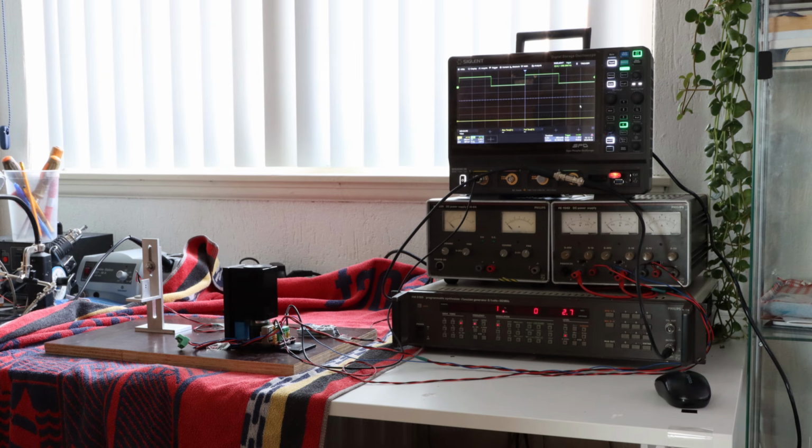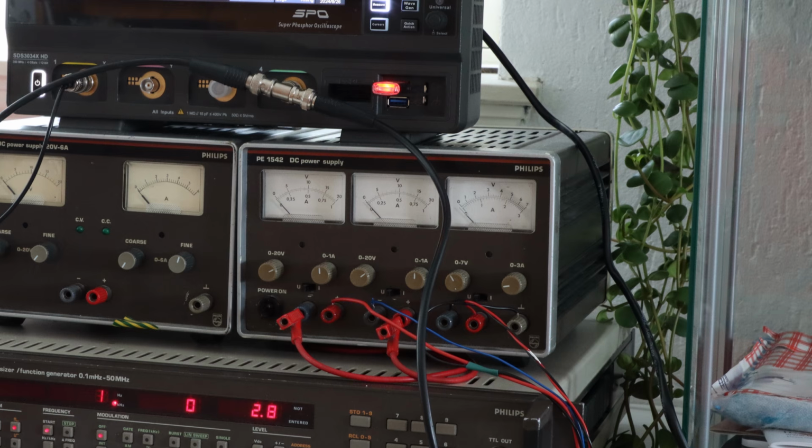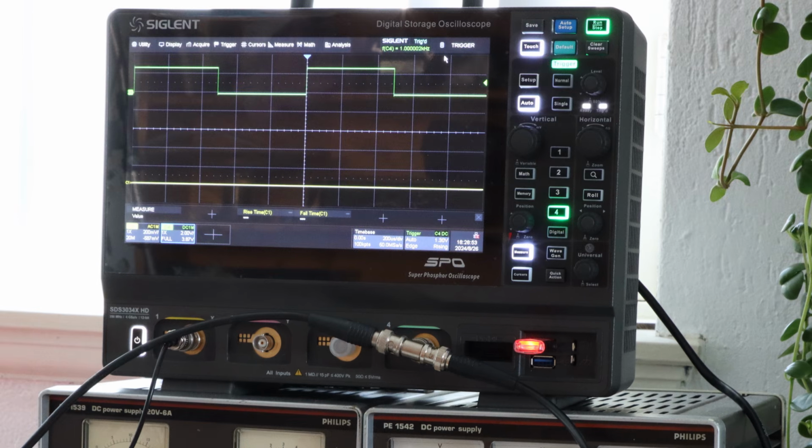The plus 15 and minus 15 volts and ground connections were supplied to the board by using two power supplies chained together. The gain is set using a third variable voltage supply on connector K1, and the signal output of the board is fed into a digital oscilloscope.